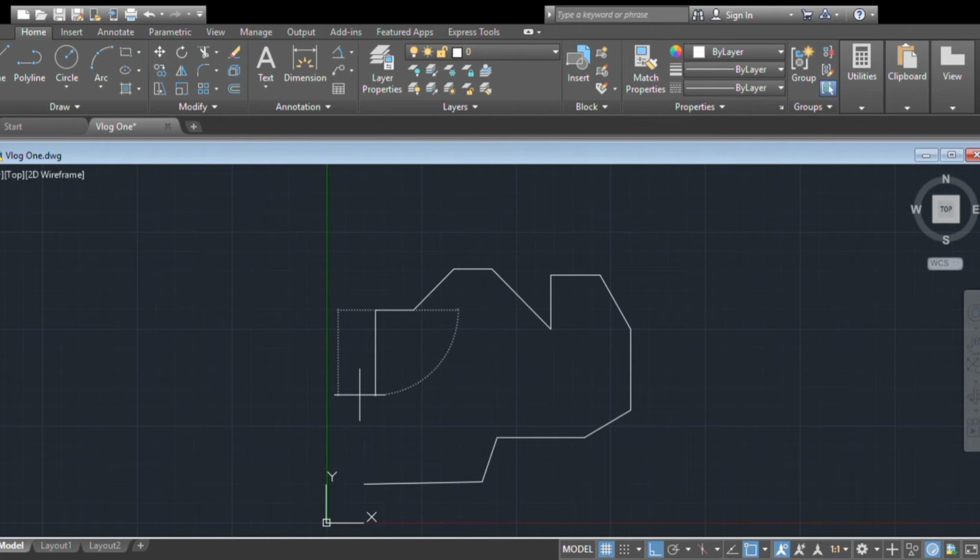Next is the line going downward. So we have to type 2.3 with the length at 60 degrees. So just simply type 2.3 tab 60, enter. And lastly, we have to connect the last line from the base or simply close.